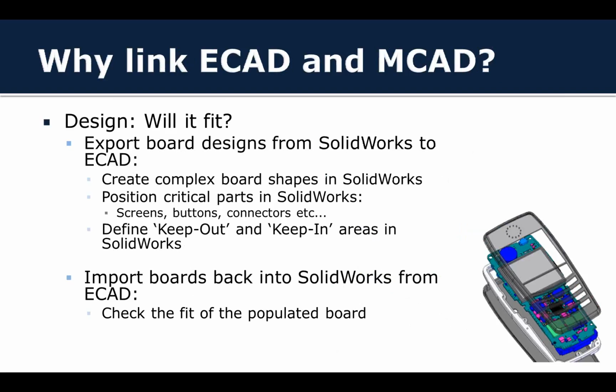So why would you even want to consider interchanging your ECAD and MCAD information with each other? Very often it's 2 different people in the company. But on the mechanical side of things, very often it's a form and fit type of question. You have complex board shapes as products are becoming more and more complex. You need to position critical components, push buttons, screens, connectors.